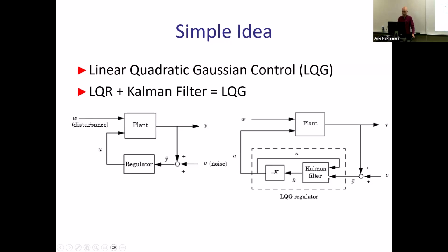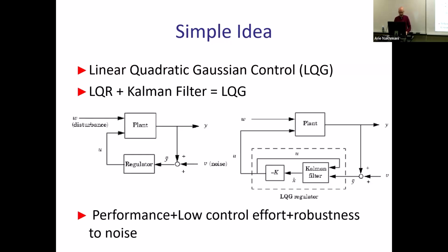But think about that as transfer function from that line to that line. So you can think you have single input, single output, practically speaking, between that Y bar to U. So you can think about all of that block as particular transfer function. And this is what we want to find. What is the transfer function, which includes Kalman filter and LQR as a block, as transfer function from error to input, control effort? This is our goal.